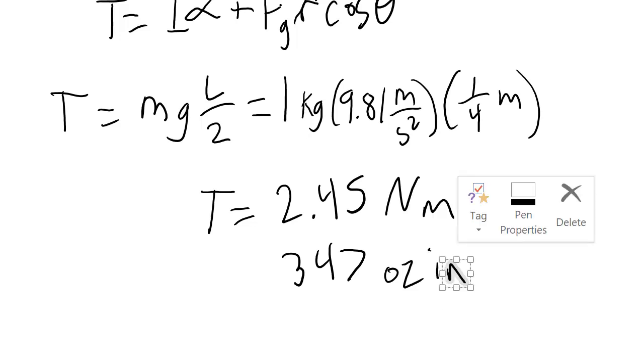So note that the amount of torque in this case required due to the force of gravity is much greater than the amount of torque that was required just due to the acceleration. Of course, this won't always be the case. If we had assumed a much greater value of required acceleration, then that source of torque requirement would have dominated.